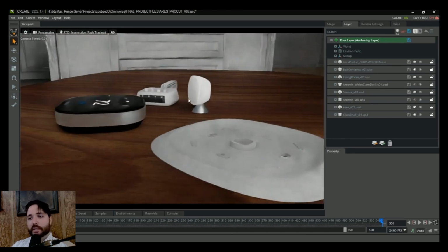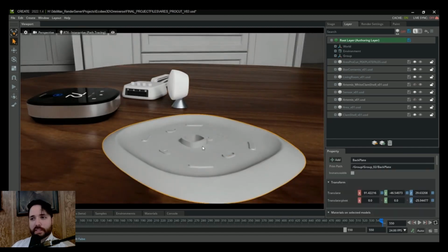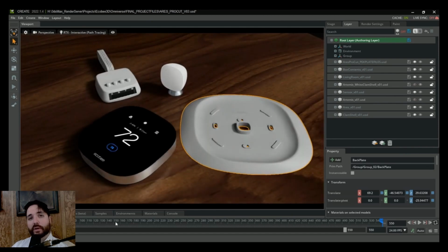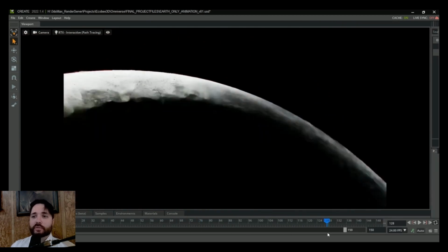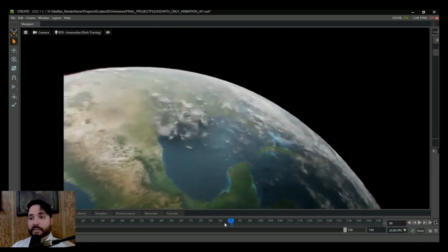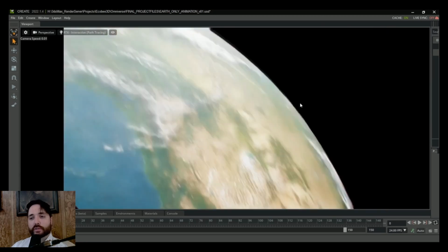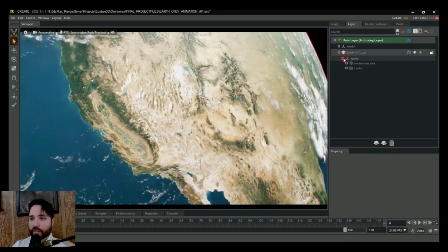And what's really cool about sublayers is that they propagate across all of your project files. So for instance, if you change your USD file, it will be loaded in the same way across all your other project files that reference it. You just have to be careful about overwriting them, especially when removing objects in your scene that are controlled by that sublayer. But I love the modular aspect of this workflow, as it allows for non-destructive revisions that keep all your files and your project properly organized.